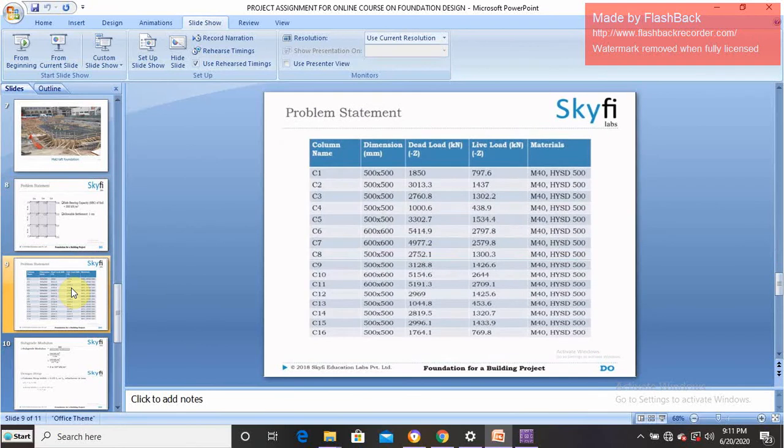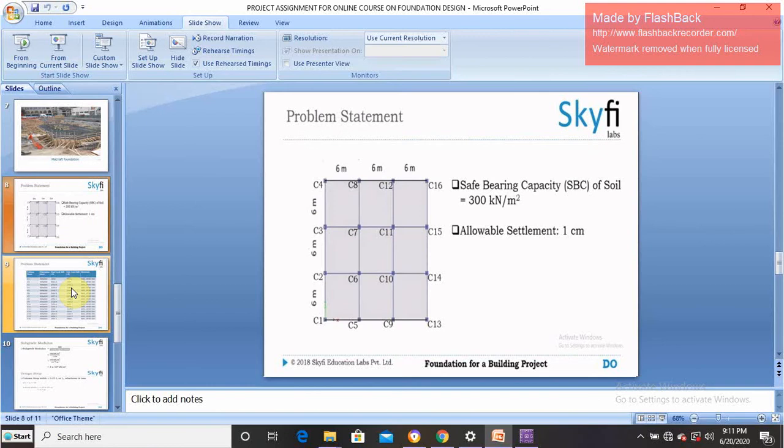So you can see here, column 10 and column 11 have 600 mm, 6 and 7 have 600 mm. So 10, 11, 6, 7. The middle 4 columns have 600 mm dimensions and the outer ones have 500 mm dimensions. So first we will select the 500 mm, create the outer columns, then we'll select 600 mm, create the inner columns. It will save our time, right?